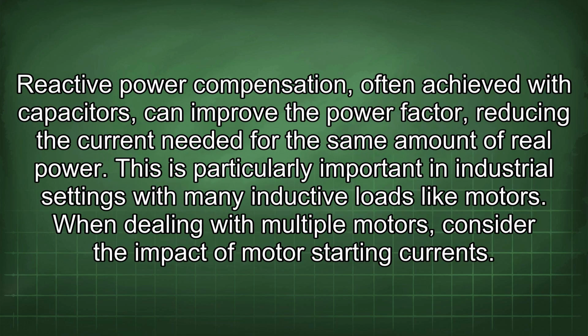Reactive power compensation, often achieved with capacitors, can improve the power factor, reducing the current needed for the same amount of real power. This is particularly important in industrial settings with many inductive loads like motors.